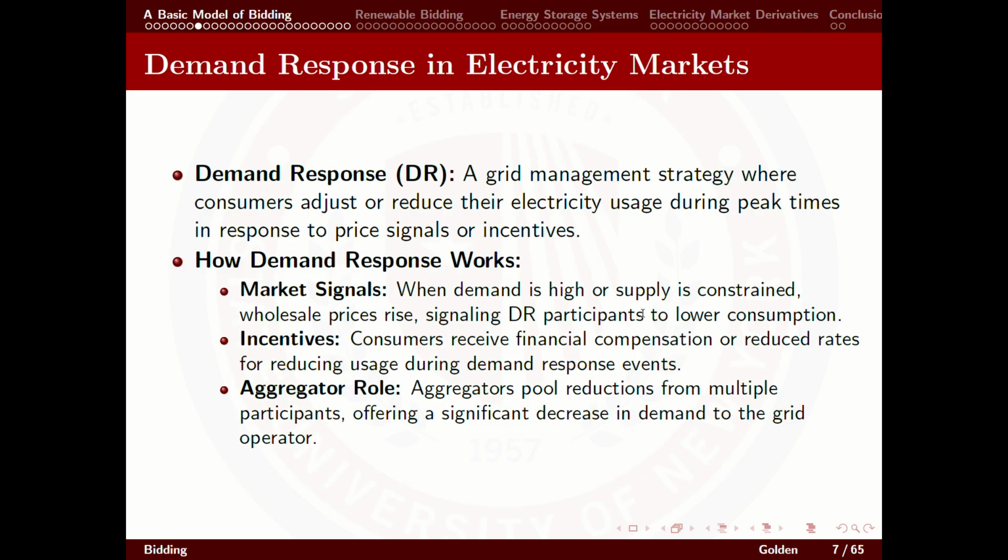We're also seeing this some out in Arizona and some places with virtual power plants, where we're encouraging retail-level consumers with rate incentives to turn down thermostats in the winter when there's too much load, and then turn off thermostats in the summer when there's too much cooling, in the idea that this will decrease the load and help prevent shortages. So we're using retail consumers as a dispersed resource.